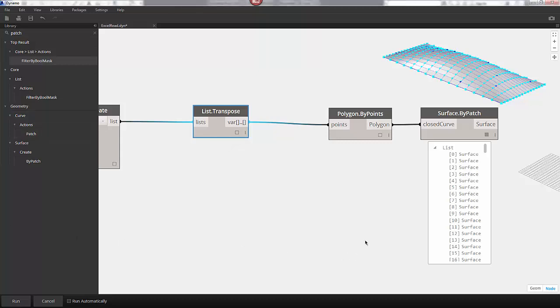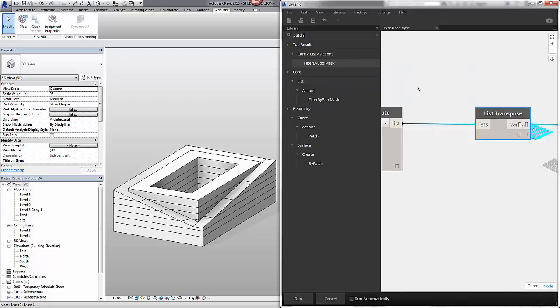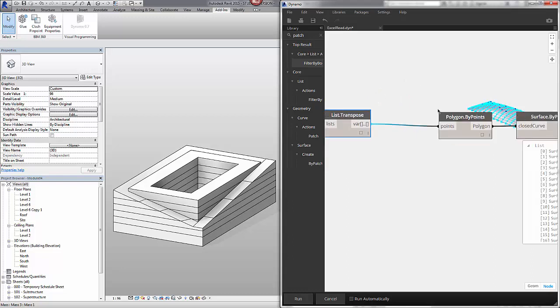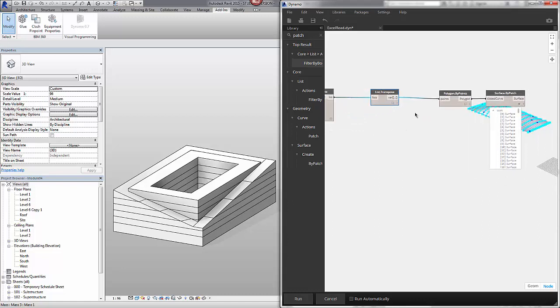The first step we want to do is create adaptive components from these polygons. Now we can jump right into these surfaces and analyze a good deal of them, but what I'd like to do is show how we can have this analysis show up in our Revit file so that you can update given sheets or color certain panels in a certain way to represent that in your documentation rather than being wholly contained in Dynamo. So let's zoom out a bit and consider what we're using to drive our adaptive components.